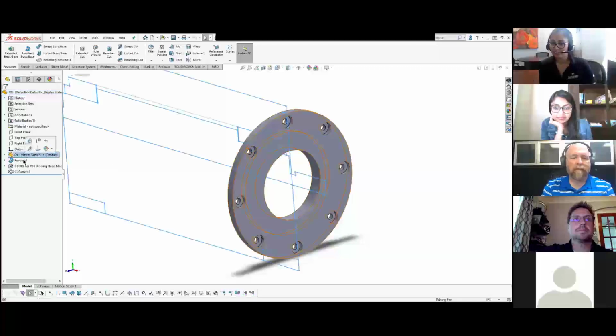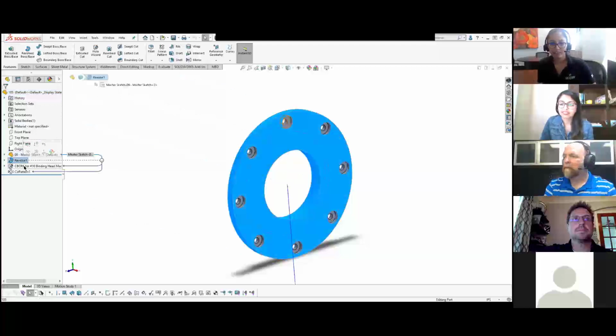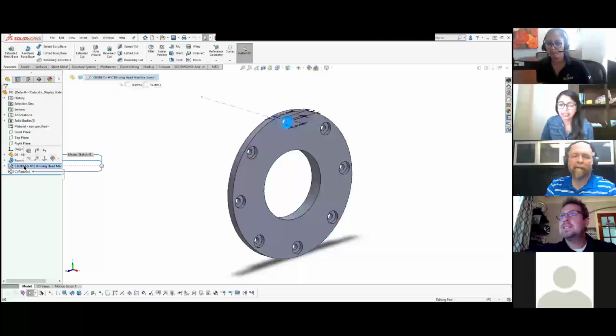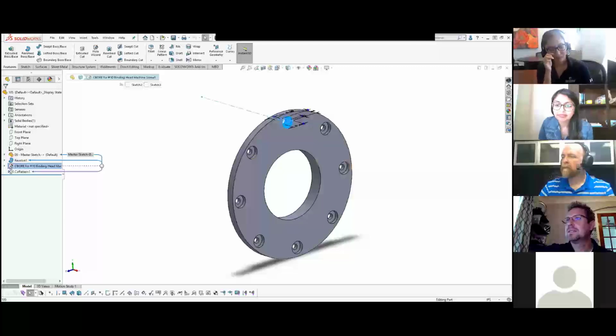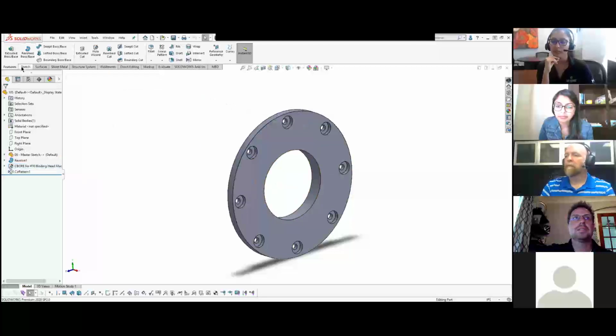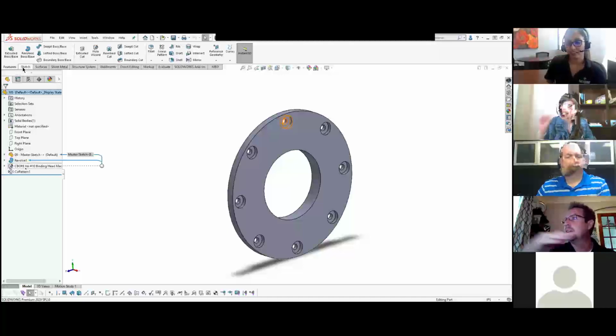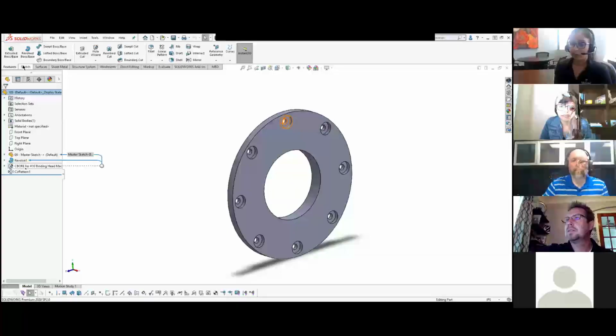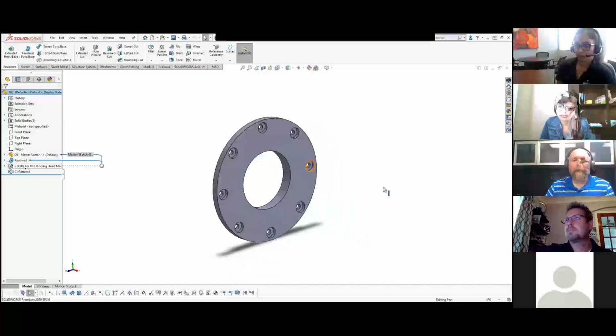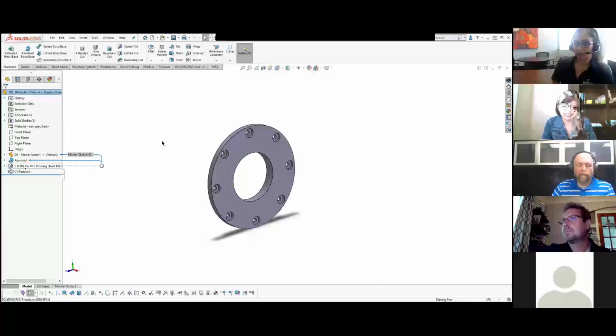Gregory asked Darcy, how did you change from one axis to another in a 3D sketch? Tab. Tab key. Tab is your friend. David said Z vertical changes horizontal vertical relationships. How do we change them? Again, needing that vertical Z-axis for aerospace stuff. Just in a 3D sketch, or do you think he's talking about the coordinate system? I think he's changing the planes. I think the only way is modify sketch that Tim showed, right? That's the only thing that actually changes the vertical and horizontal.